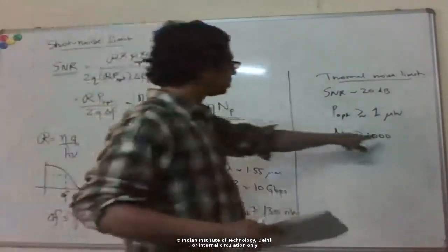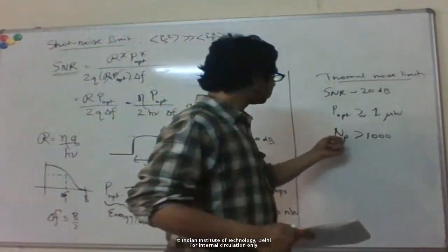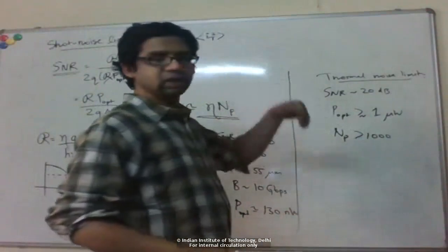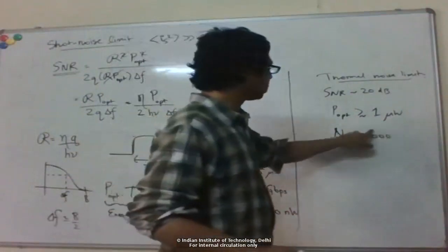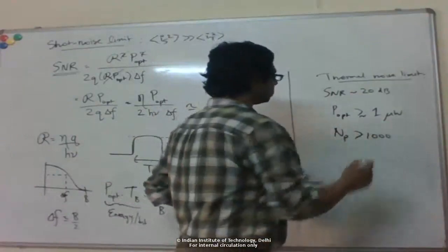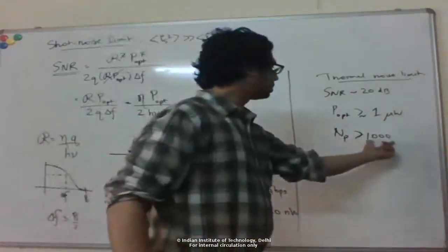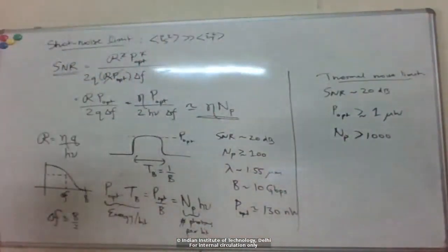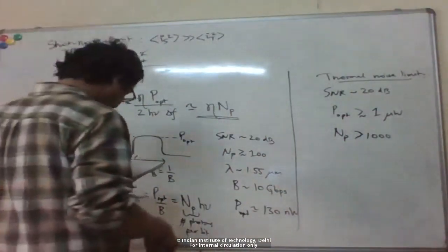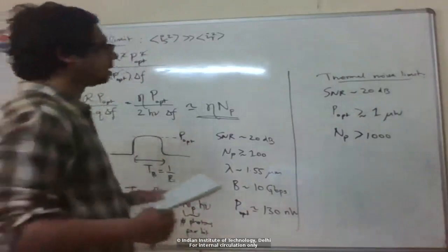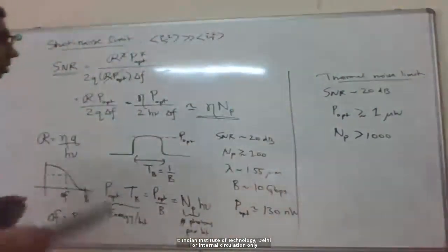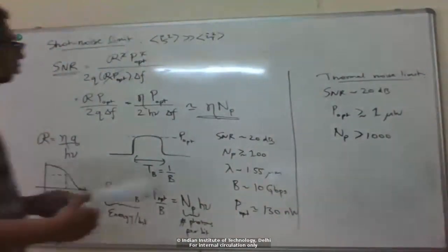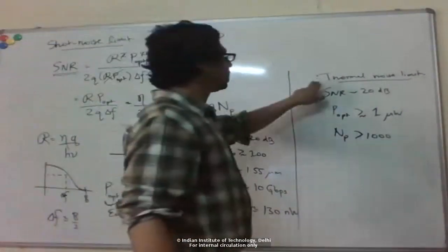Okay, so recall this discussion about the Poisson distribution we were having, and then approximating it with the Gaussian distribution. So this is basically the average number of photons we are detecting per bit, right? So you can see that this number is much bigger than 1. So this Gaussian approximation works. Specifically for the shot noise. I mean, thermal noise is pretty much Gaussian. But yeah, so for typical pin photo receivers, we are typically in this limit.